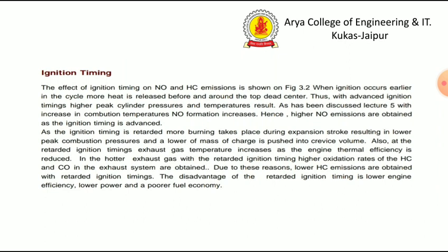Ignition timing also affects the formation of NO and HC emissions. When ignition occurs earlier in the cycle, more heat is released before and around top dead center. So with advanced ignition timing, higher peak cylinder pressures and temperatures result, as has been discussed before. With higher combustion temperature, NO formation increases, hence higher NO emissions are obtained as the ignition timing is advanced.